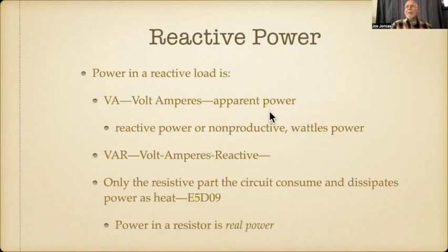So that's the apparent power. If you are running a huge resistive load, or just light bulbs, which are simply resistance, that works. But if you're running your vacuum cleaner or a motor, that is a reactive load. And the actual power dissipated will not be that.